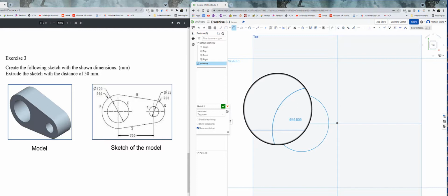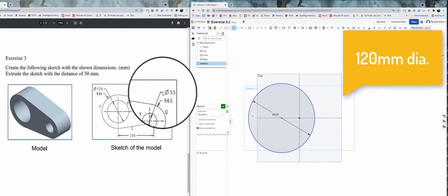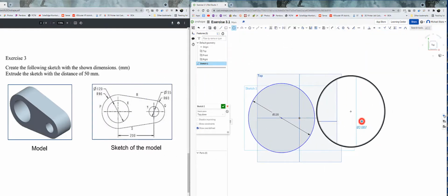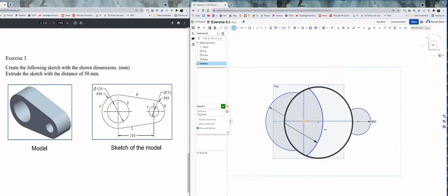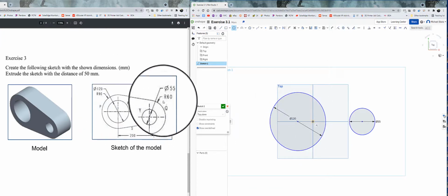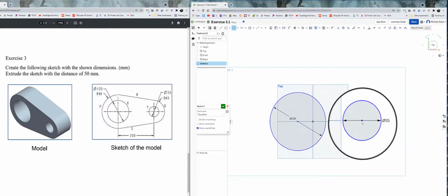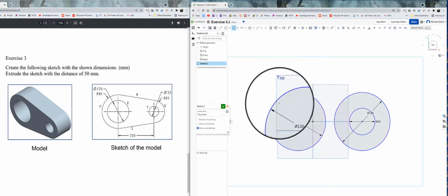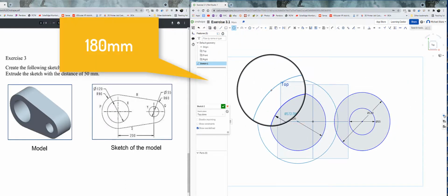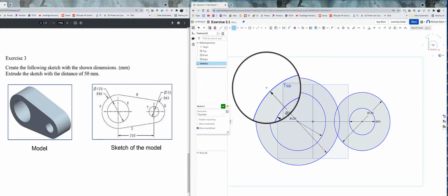So they tell us that we have a diameter of 120. Sorry, here, and the other one is 55. And then we have the outer circle. So this is a radius of 60 that comes around the outside edge. So we know that it could be a diameter. So I'm going to come in and draw another circle. And I can do 60 times 2. Looks like that. And then over here comes out. And that's a 90 radius. Or 90 times 2. There we go.